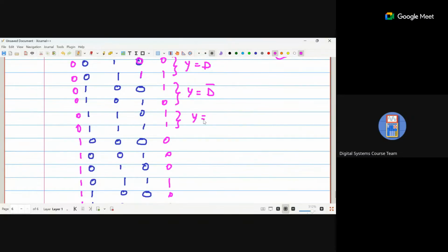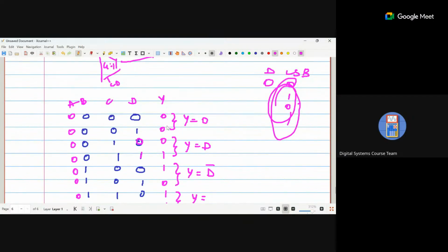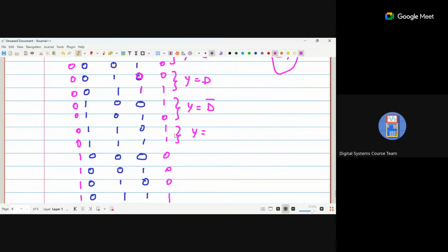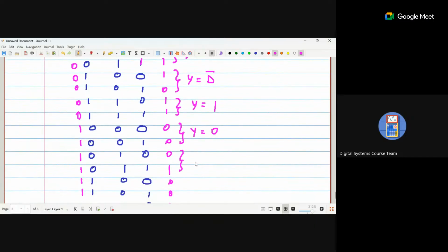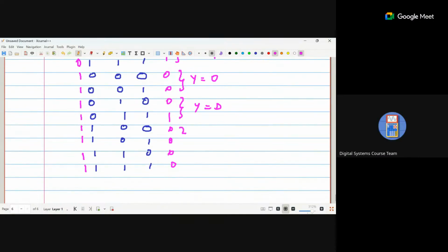So the first thing you have to keep in mind is, if both the outputs are same, it means that y will always be that. If both the outputs are different, that is when you go to the variable and check y follows which particular variable. So if you see here, both the values are same, then what will your y be? 1. And here, what will your y be for this? 0. And for the next one? It will be the same as D. Correct. And here y will be 0 and the next one also y will be 0.